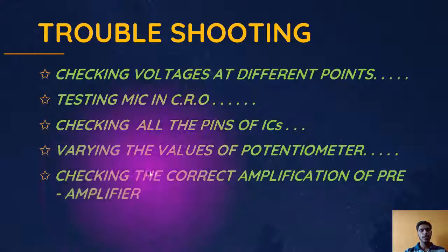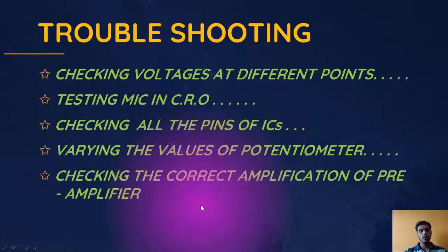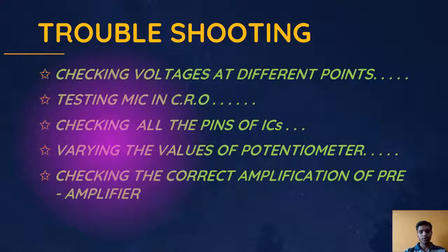In my circuit it was important to give the amplified signal to the JK flip flop, so we need to check that we are correctly amplifying the signal or not.